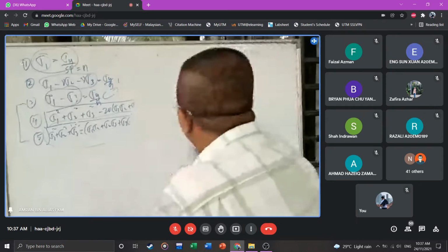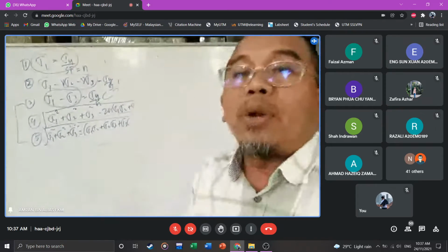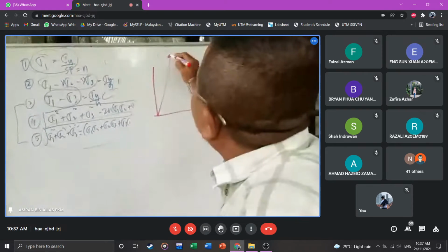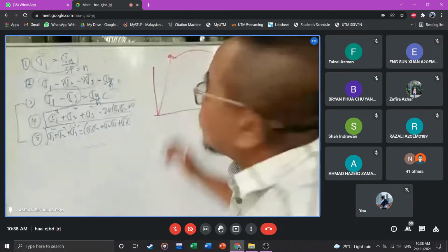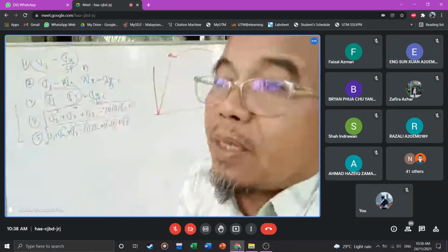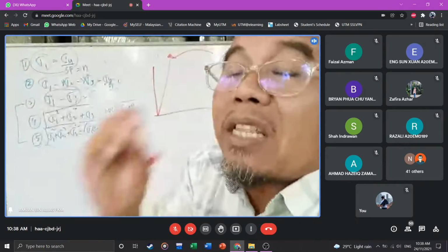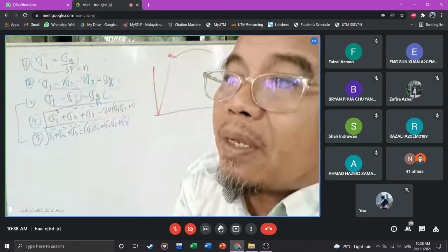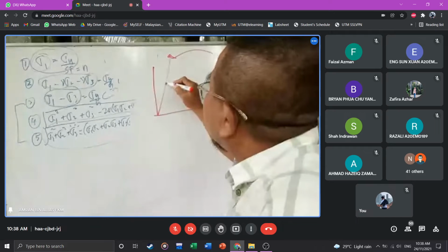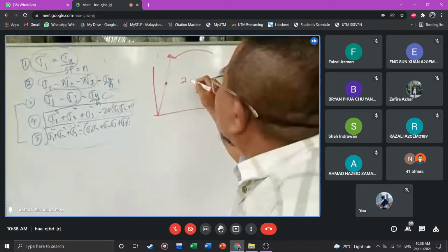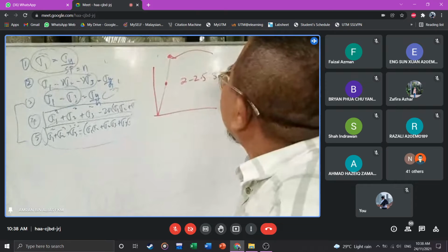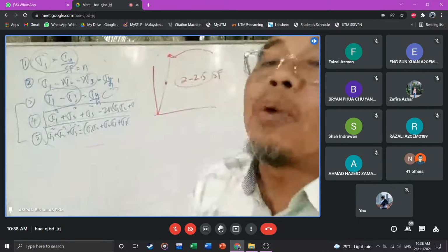So now, you know that we don't want to design things with a safety factor of one. So for normal things that we design, what is the safety factor? Normal engineering product, what is the safety factor? 2 or 3. Yes, exactly. So around 2 to 2.5 safety factor. This is a normal product.